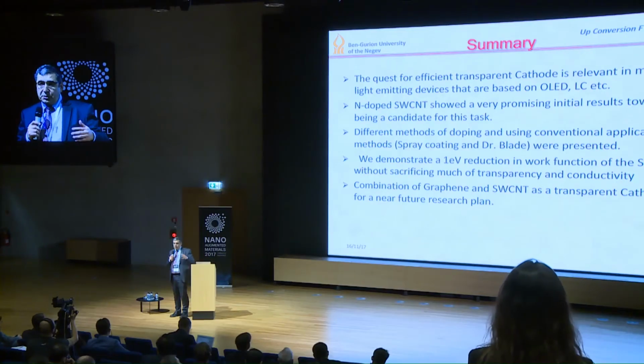This is not the topic of this conference, but I will get into it. There are 3 main applications. The first application, which I think is the best one, is basically to have a device that is the sensor of a LIDAR in the short wavelength infrared. Short wavelength infrared, namely 1500 nanometer, is very attractive for LIDAR because it's not in the visible. It doesn't get dazzled by the sunlight, and the laser is eye safe. So there is a good tendency to go to a 1500 nanometer spectrum.